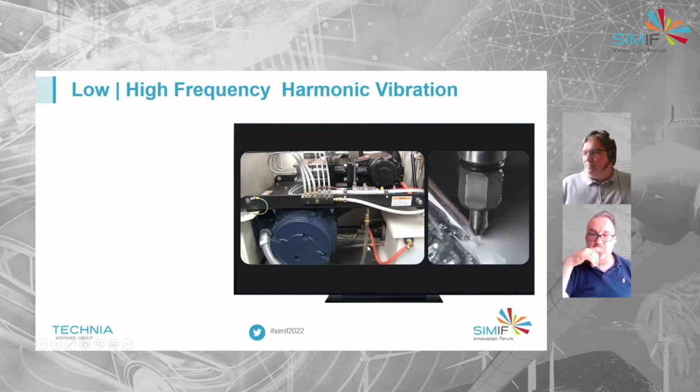So we've got two parts of this assembly that are going to create frequencies and vibration. The first is this big pump. This is the water coming from the inlet and being forced up to the nozzle. And then we've got the nozzle itself, where it's spewing out the water at high pressure, which has got a frequency to it from the water coming through, but then also applies, going back to basic physics again, an equal and opposite force going up as it's pushing itself out.